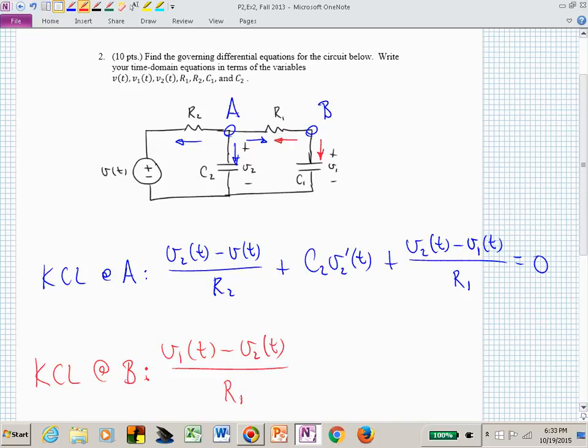And that should be the negative of that blue current that I just found earlier. And it is, isn't it? This last term in my first equation, I've just written the negative of. And I now have one more equation for the current leaving node B, and that's the current vertically down from node B, and that's C1 V1 prime.